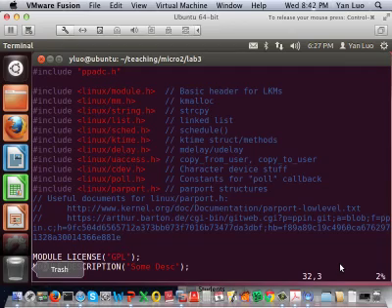For example, for this parallel port, you will see that we actually rely on the underlying parallel port APIs, layers, which is not necessary when you use a serial port. So that's one difference. Also, depending on whether you will use a character device to interact with it or not, you may or may not need to have the character device registration.